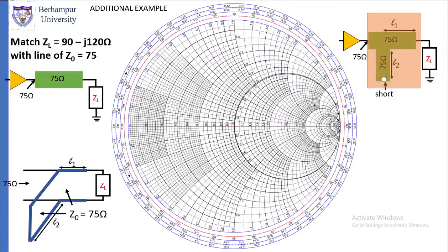Now, instead of one short-circuiting point, you can use many short-circuiting points, because when you connect top to the bottom using a wire or any conductor, that conductor has some inherent inductance. So to reduce the inductance, if you use many conductors in parallel, the inductances will be connected in parallel, and that will reduce the value of inductance. So that is why you require more number of short-circuit points. Instead of 1 point, if space permits, you use 2 or 3 points.